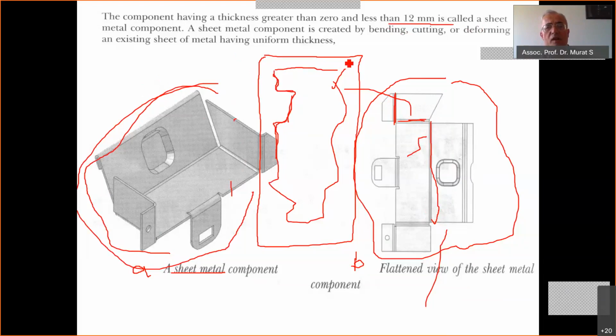Well, this is important. This is the threshold value. In identifying the work as sheet metal work, we use this threshold. If the thickness of the stock, and the thickness after folding of each of the combined features, is less than 12 millimeters, then we say sheet metal. In Turkish we say saç levha. Using a sheet metal, while folding it along specified paths, we can obtain the object in the desired form. It is called a sheet metal component, and the process is called sheet metal work.